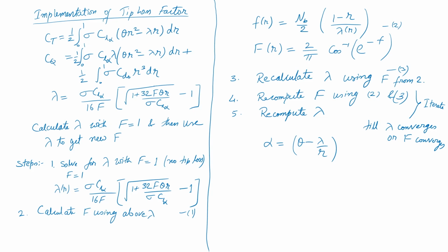I can give you a linear twisted rotor, or I can give you a hyperbolic twisted rotor. In your assignment you will get to check all those things. What does my hyperbolic twist do? What does taper do? I think I have not given you a taper problem, but I will probably give you the twist problem. So look at the different effects of twist and see how it affects my inflow distribution. I will plot lambda, and if I use twist, you will see my lambda start becoming uniform. When I do not use twist, you will see the lambda is more non-uniform.